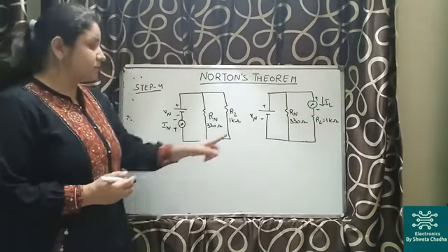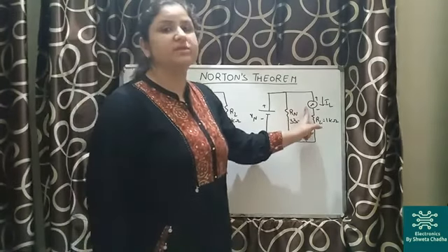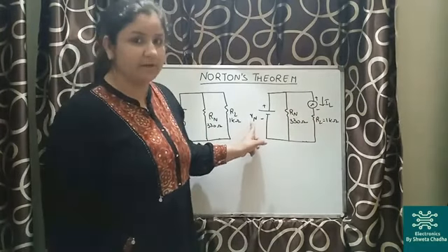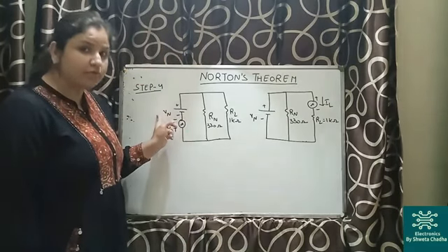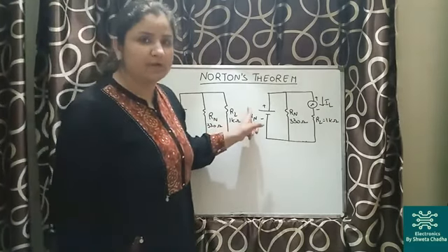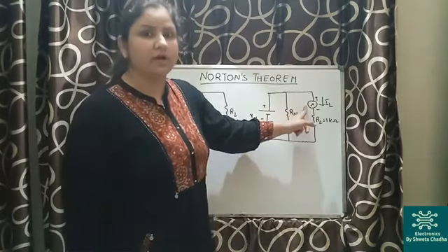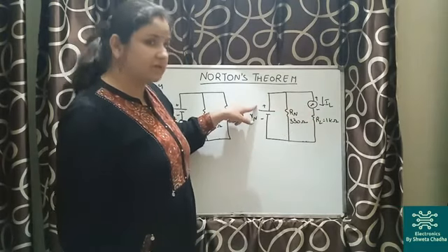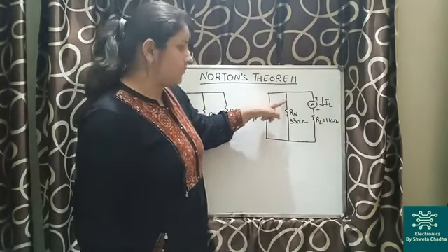After which the ammeter will be now connected in series with RL. Do not change this voltage Vn. Whatsoever Vn you have measured over here, set over here, do not change its value now. So the last step is going to be the calculation of current flowing through RL. So what are going to be the connections? The positive of supply will be connected in parallel with RL.